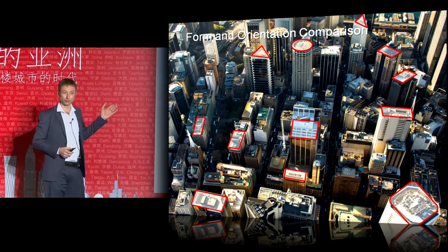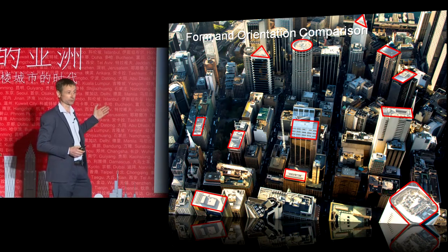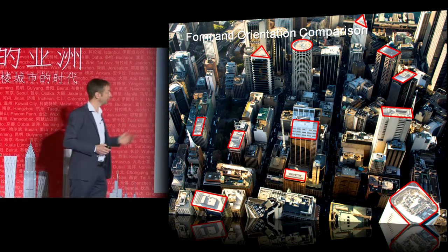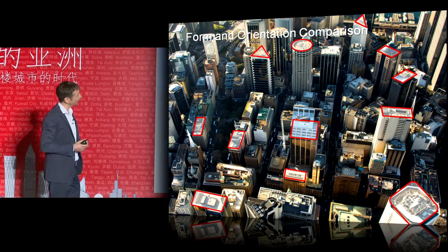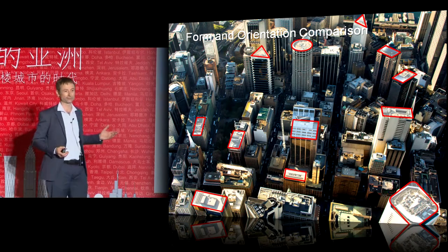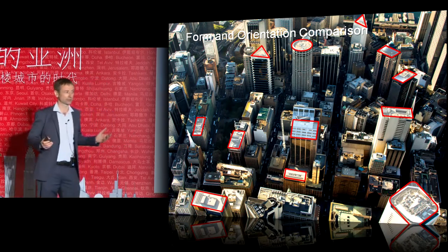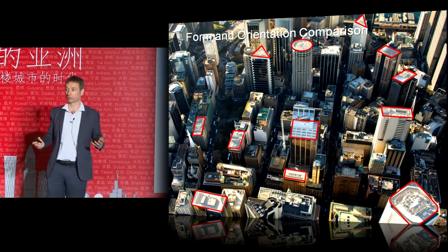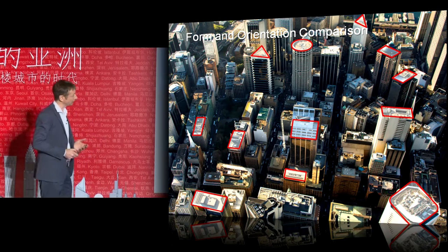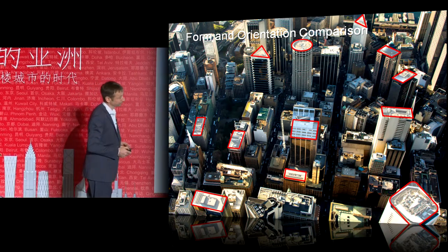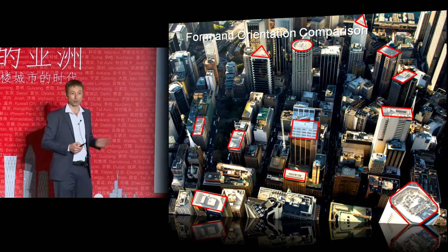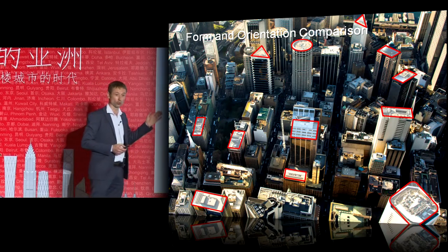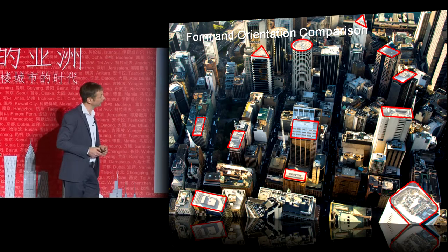This is a view of the tops of buildings in Sydney, Australia. It's a great big picture, actually, and when you look at it, you can see the diverse range of different types of building shapes, and you ask yourself whether those buildings have been shaped because of any environmental reasons to provide more energy efficiency in the building or not. For example, down there, we've basically got an octagon. Here we have a square building, probably the 1.16 to 1 ratio, ideal for a temperate climate, facing north, which of course is where the sun is in Sydney.